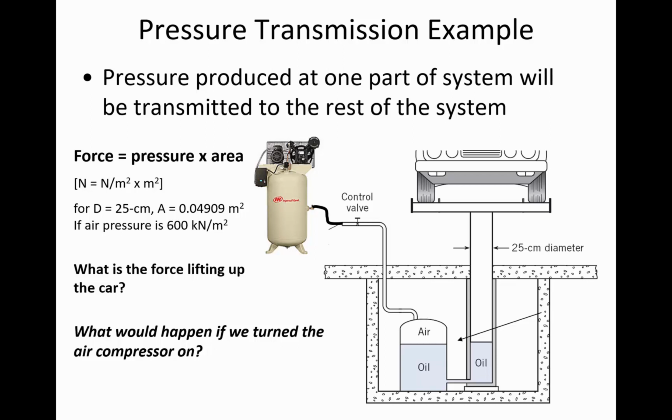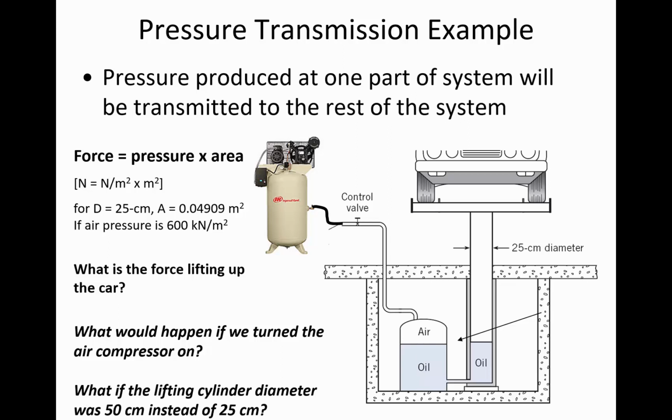And so that means if the car is higher, then the oil is going to now be up here, some distance higher. And the way that it's able to do that is that there's going to be more pressure inside the air component. And so you just use the hydrostatic equation to find the new pressure at a certain elevation. Okay, thanks. Yeah, we'll do examples like that.